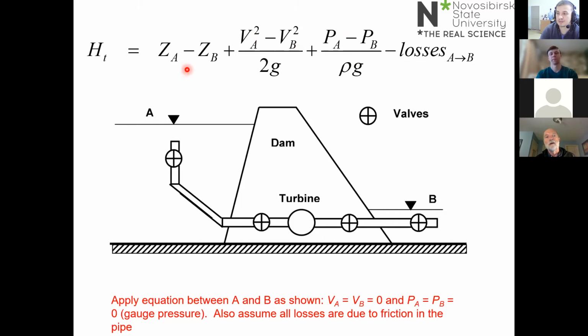And so that means that the energy that is available to that turbine is due to the difference between the physical head and the losses that occur in the pipework. And that's the statement that is behind the next statement that people often make. Most hydro turbines are head-driven. They are driven by their head, which represents the available potential energy. For some reason, hydropower always works with potential energy in meters rather than in units of g times h, which is the proper energy term per unit mass.